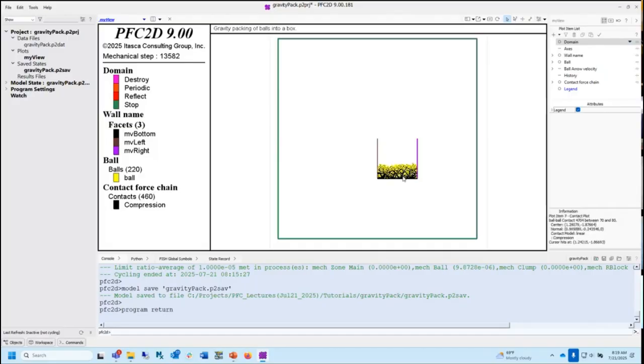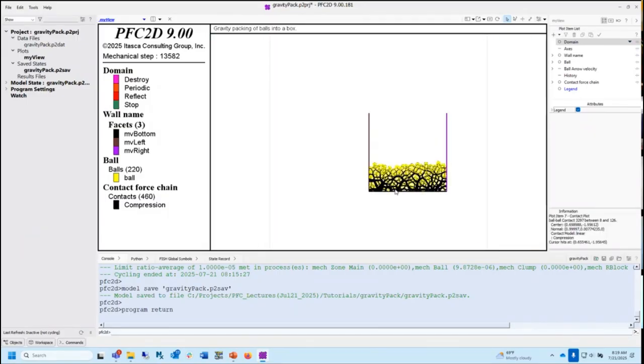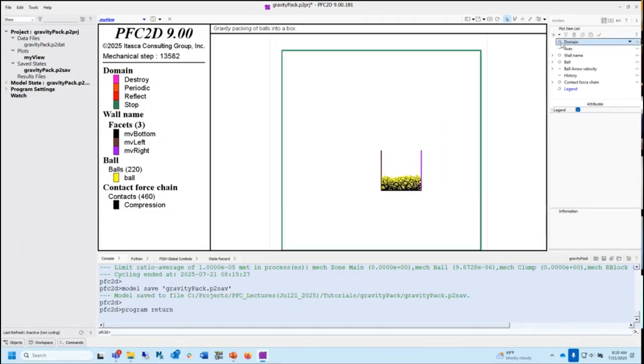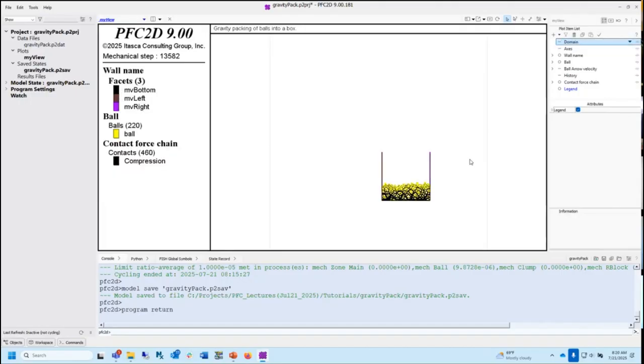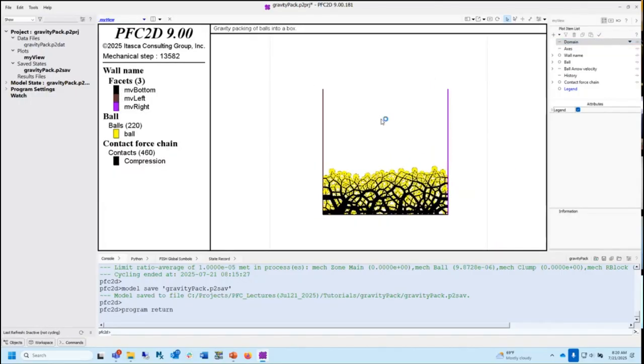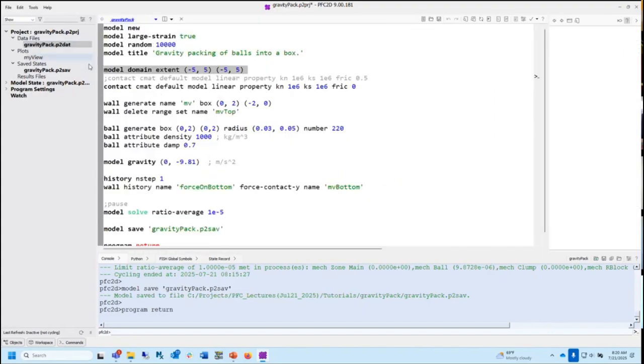And we want to make that region relatively small. The reason we do this is so that we can make that cell space adaptively make itself recursively smaller as needed just where the particles are. And if you have an enormous domain, then you have to have an enormous cell space, even though all your action is only happening in one small area. So that's the reason. Turn that off. Go back to this. What else we got going on here?